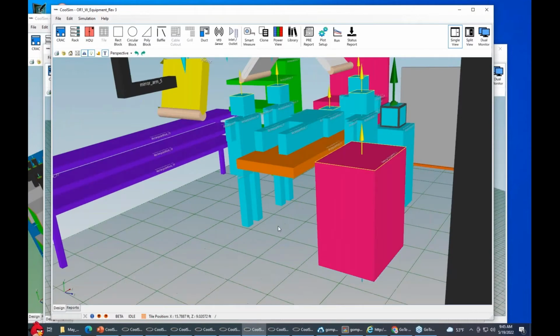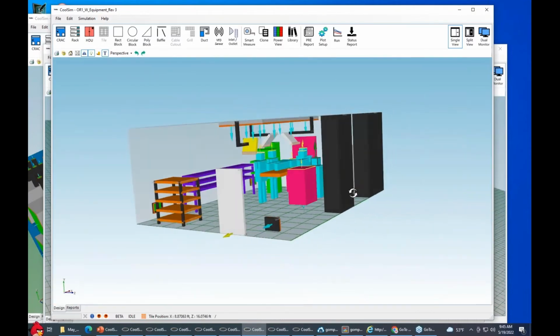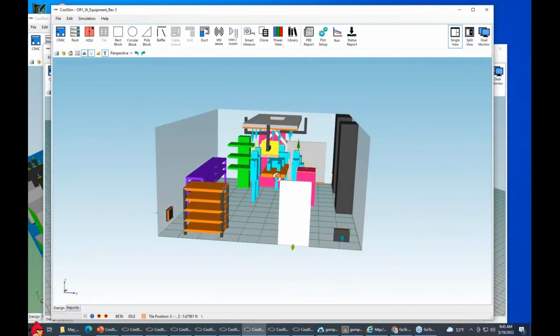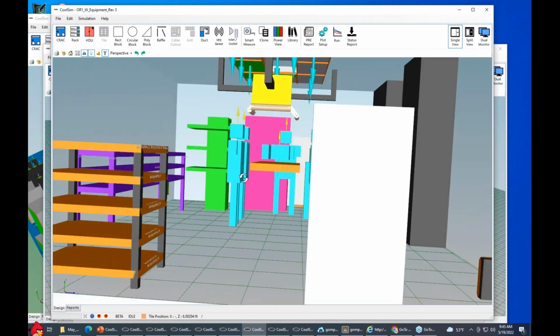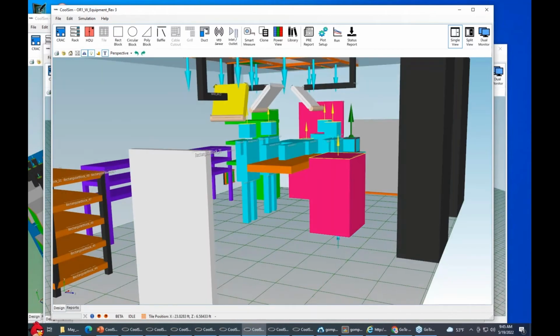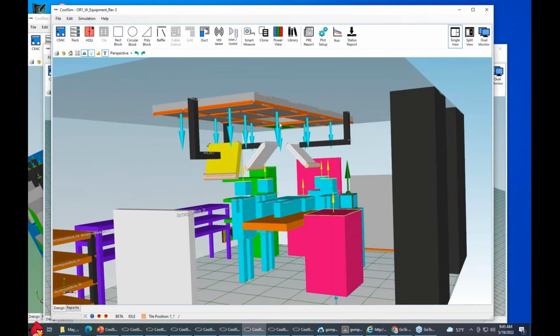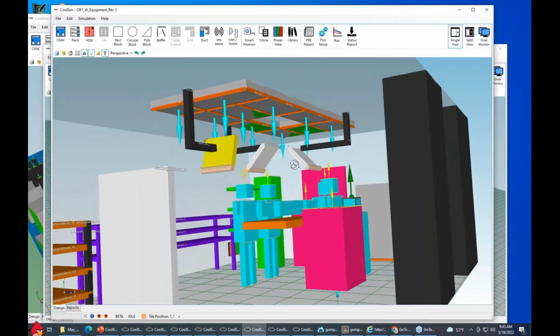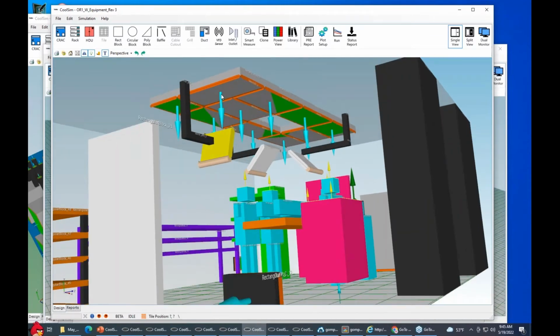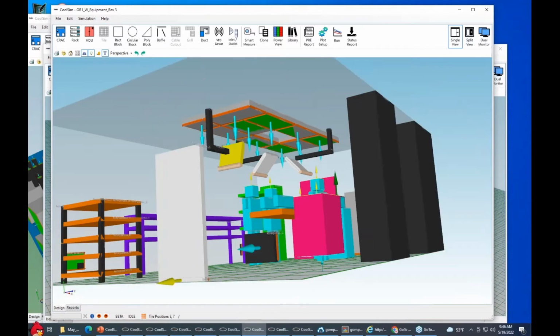This is an operating room. So let me back up and show you that this is an OR, okay? And what we've got coming out of the ceiling are inlets. These are laminar downflow units. These are very typical in an OR where you'll have these panels that diffuse air, very straight and laminar flow down through them into the environment.